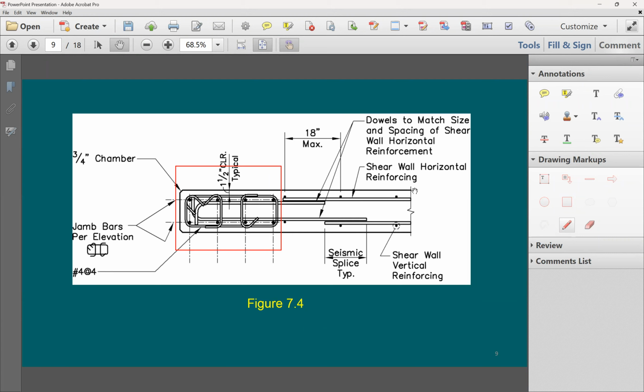You can see here for number 5, the reinforcement for just one bar is going to be 0.31. If I take this, divide by what is needed, times 12, it's going to give me the proposed spacing, the needed spacing. Someone can do it differently, but let's follow this example and then you can do it differently if you like.